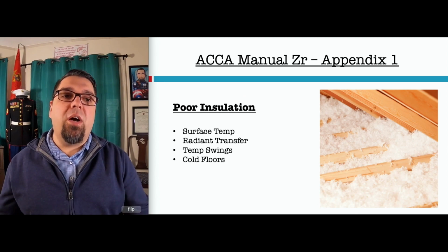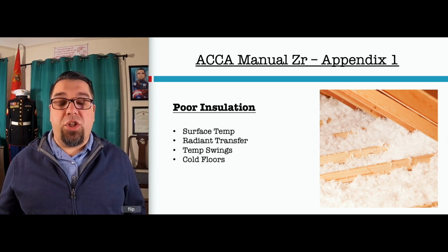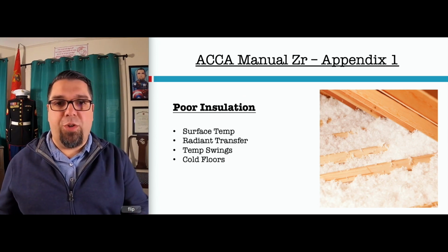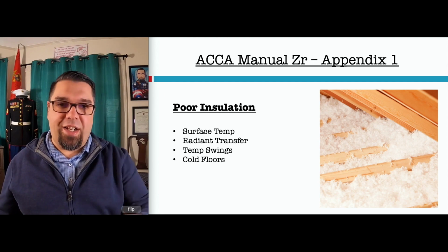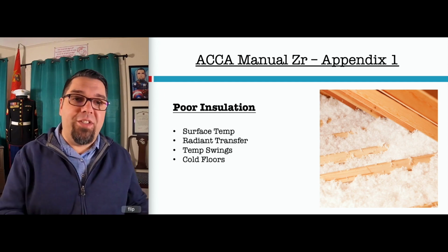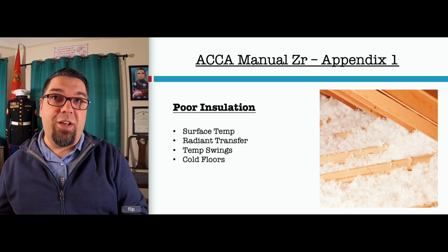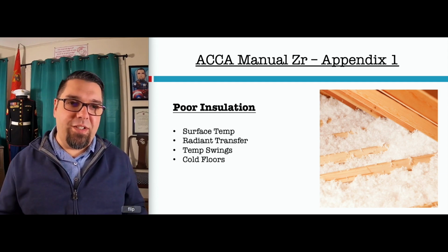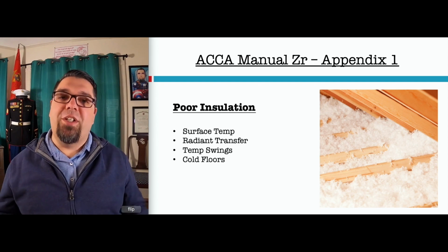All right, so let's talk about insulation. Poor insulation, obviously, infiltration is the first one. We really should talk about that first, but it's in the next slide. You want to air seal before you insulate a house, right? Just like you air seal a duct system before you insulate a duct system. If air is moving through the insulation, it does no good, all right?